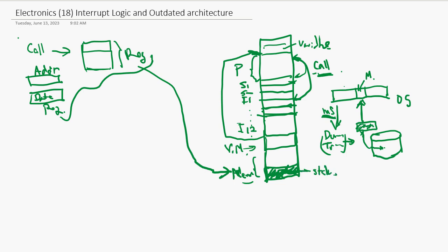And inside the call, if you have another call, from here the call program jumps to another call, so it's saved again, as stack 2. So the stack grows from the bottom of the memory all the way toward the working memory area, right? For example, this happens when you have a recursive program.